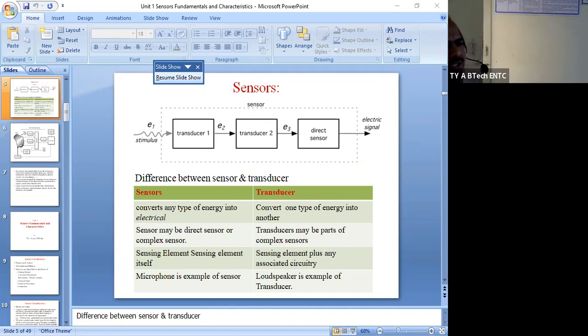So similar to sensor and transducer, all the microcontrollers are capable of measuring a digital input or digital signal provided by the output of any type of sensor. If the sensor is providing digital output, that is yes, no type, high, low type, then any controller you are able to use. But if the sensor is providing output in terms of analog quantity, like a continuously increasing or decreasing structure, change in voltage, change in current, resistance, capacitance, inductance, then for some controllers it is not possible to measure such gradually increasing or gradually decreasing parameters or quantity.